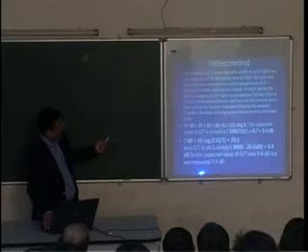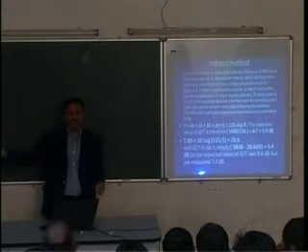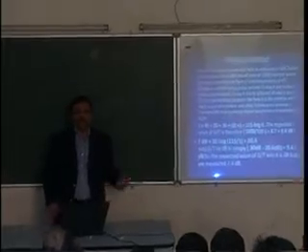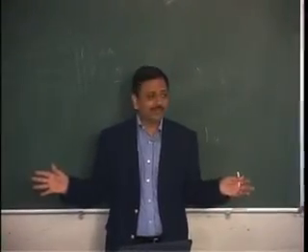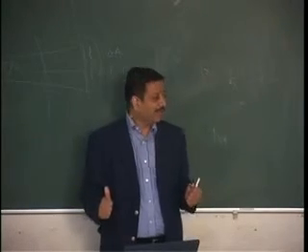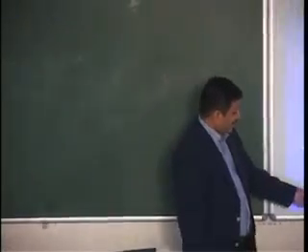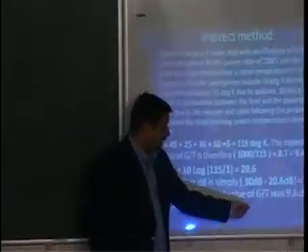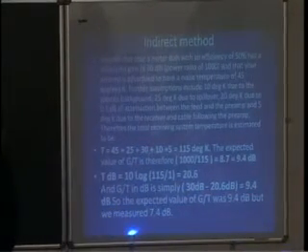Another indirect method is that we can compare two antennas together. One antenna we already know has been calibrated, and we can compare this antenna with the calibrated antenna and see how the G by T performance is. But there is some error there. Here, we expected a G by T value of 9.4 dB, but what we measured with the comparison method was 7.4 dB.